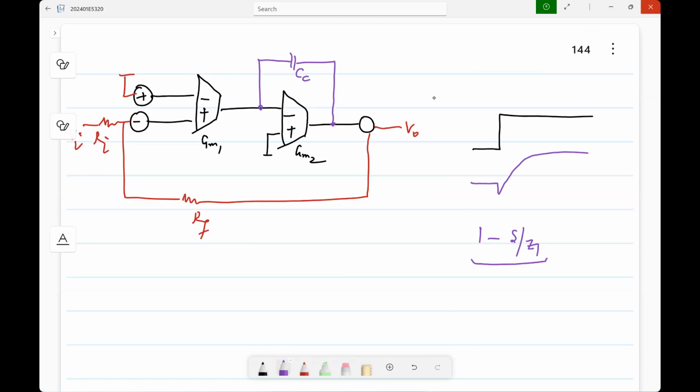If you have a left half plane zero, it's like prediction. When the speed is decreasing, even if it is not decreased below the desired value, the fact that the speed is reducing, you are reacting to the derivative. The fact that you have s here means that you are reacting to the derivative. If you have a left half plane zero, the moment speed starts reducing, even if it is not below the target, you start accelerating. If you have a right half plane zero, it's the other way around. It's a stupid thing to do, but sometimes, if you have a right half plane zero, you have it. So now how do you fix the situation? You want to get rid of the right half plane zero. What are the possibilities? I'm sure you have seen all the circuits.